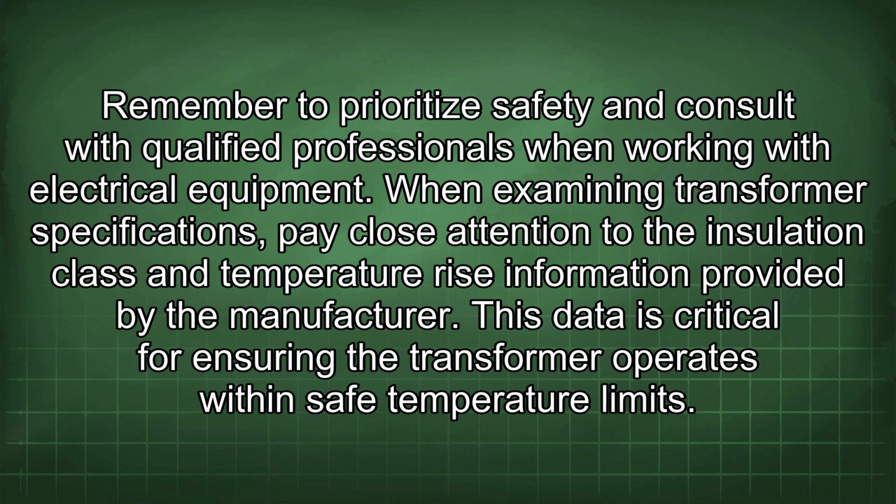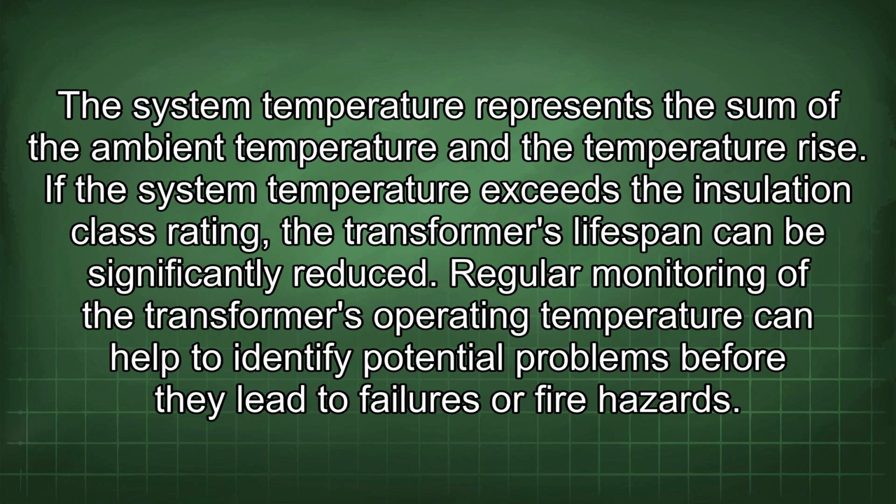When examining transformer specifications, pay close attention to the insulation class and temperature rise information provided by the manufacturer. This data is critical for ensuring the transformer operates within safe temperature limits. The system temperature represents the sum of the ambient temperature and the temperature rise. If the system temperature exceeds the insulation class rating, the transformer's lifespan can be significantly reduced.